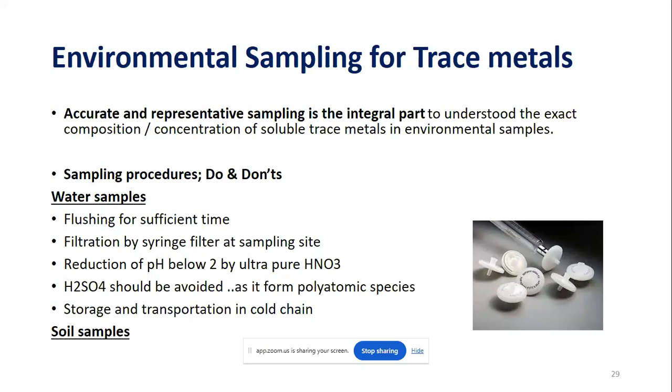is mostly dependent on how we perform the sampling, because in sampling we just collect 1 liter of sample out of an entire lake or river. So it should be representative of the actual condition in that particular lake, or river, or if it is groundwater.